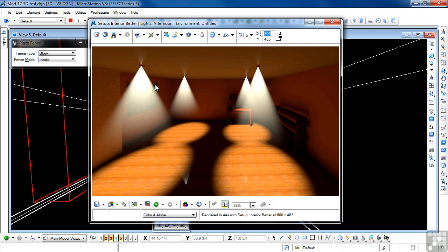There, we're done. Now you see the effect. Quite nice. I think perhaps that the scattering is too dense, and I would go back and change the density and the scattering value to much lower values, probably around 5. And that will thin out the scattering effect and let me see the elements behind the scattering. But you see how this works. Also notice that I'm seeing reflections in the floor, which is probably okay. This is a wood floor and probably fairly reflective. You can see the pseudo pot lights in the ceiling, which are attached to the ceiling itself. So that works out very nicely.